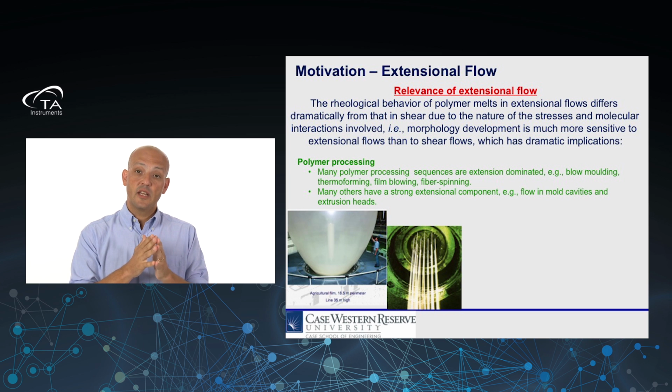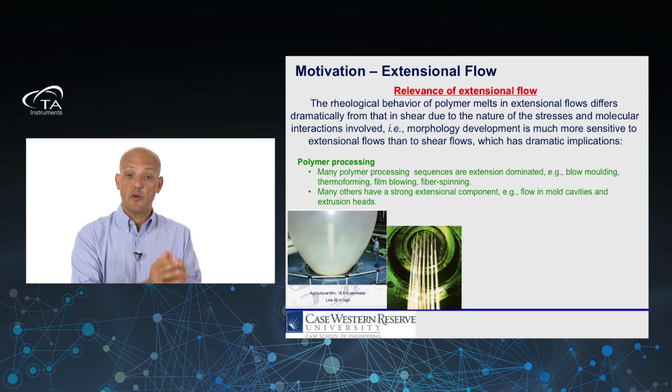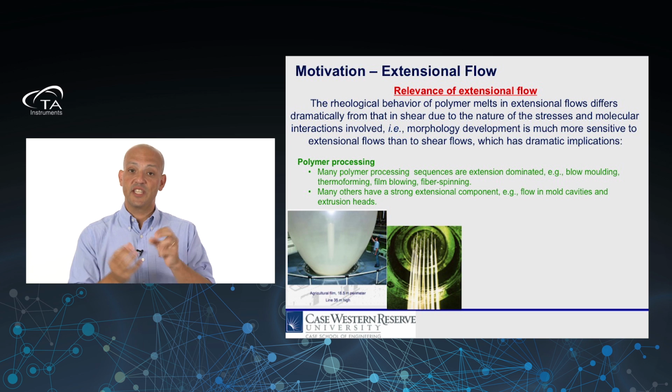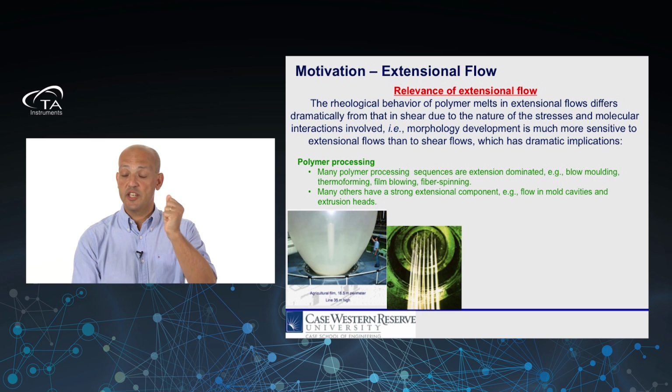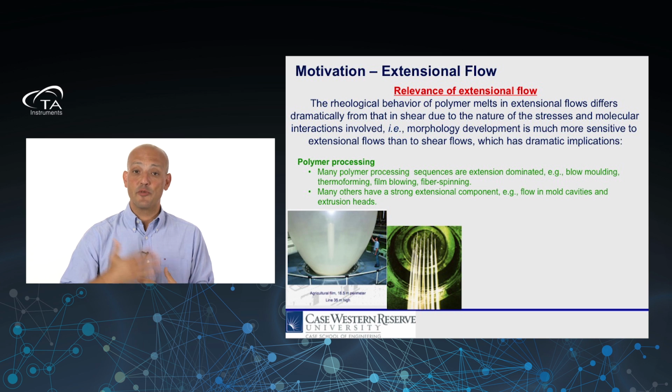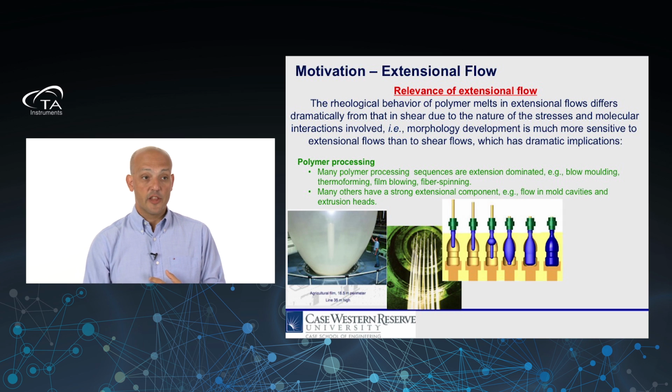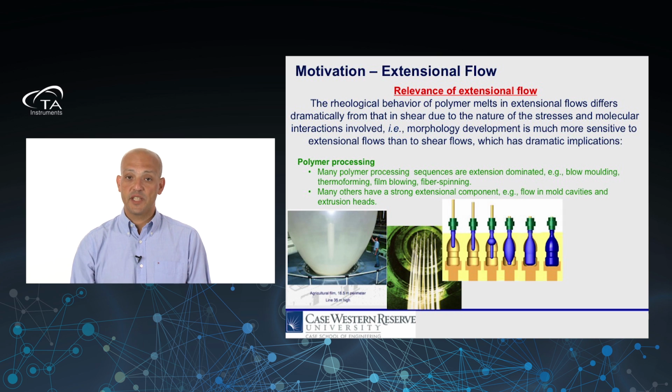And the reason for that is because now we understand much better how polymers behave and how we can control this huge stretch at the end when the polymer comes out of the die. And in these cases, this linear stretch can be as high as 100-fold or more. Another example of an everyday process that is essentially extension dominated is blow molding.